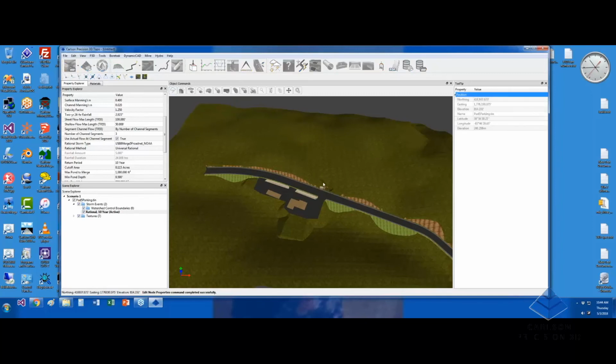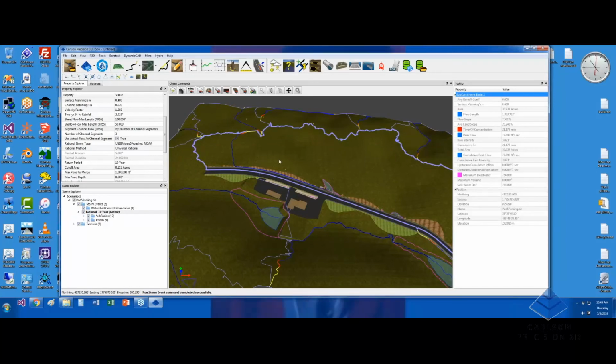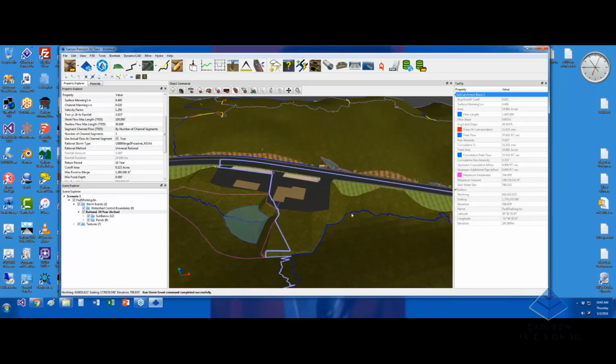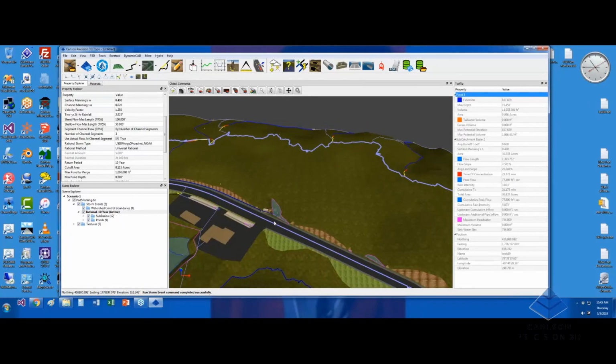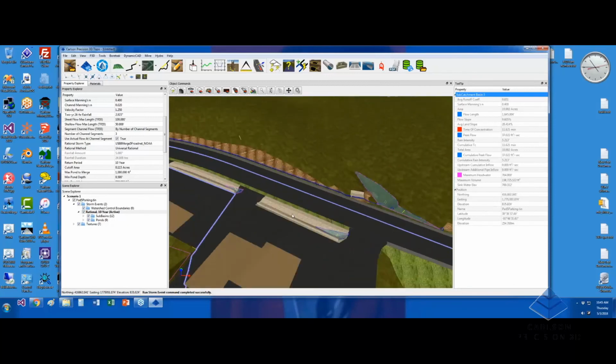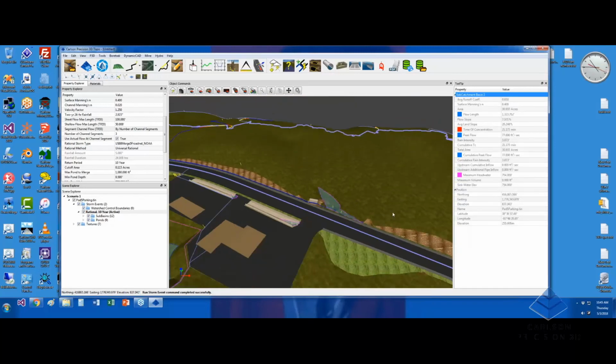I'm going to show you how to control the watershed boundaries a little bit. We have a couple of different tools for doing that. So we'll give you a good first pass on this calculation for you. But then after that, we have some really simple tools that allow you to modify these areas. The first thing that I'm noticing is that I've got 2 different ponds here. So I definitely have water buildup where I'm going to want to put culverts. I can see that there's water ponding up in these 2 roadside ditches, but they all happen to be in the same subbasins. And culvert calculations need to go across subbasins.